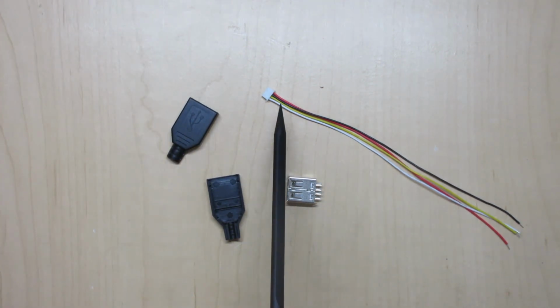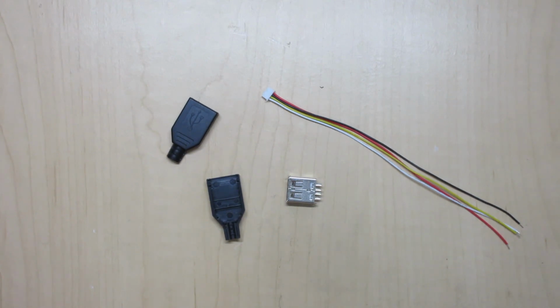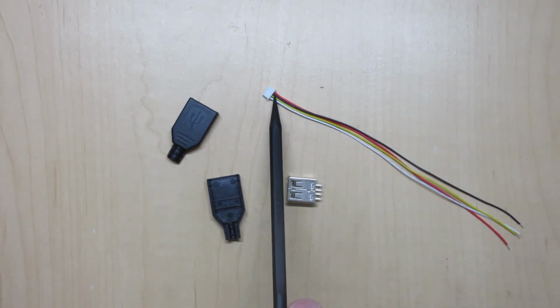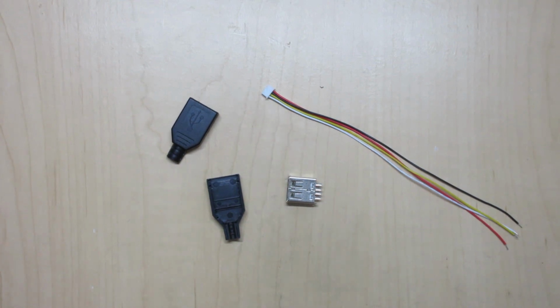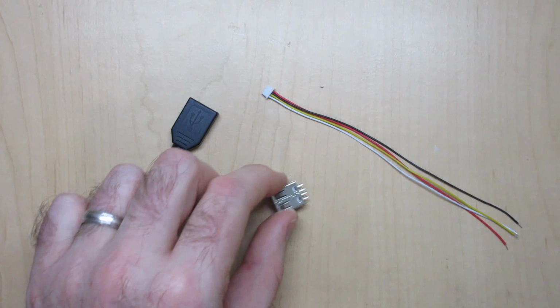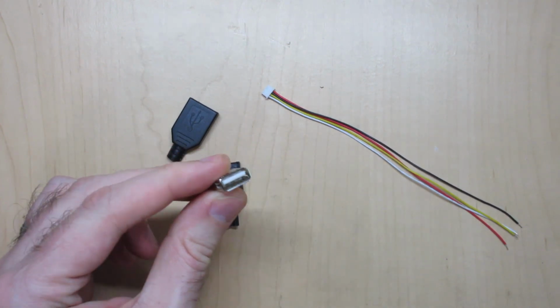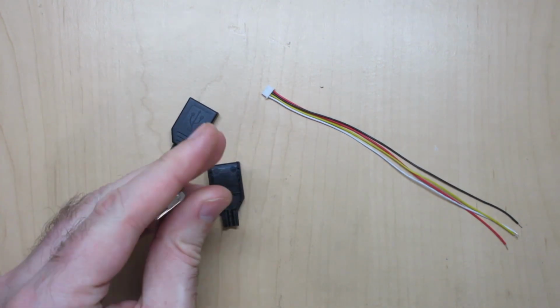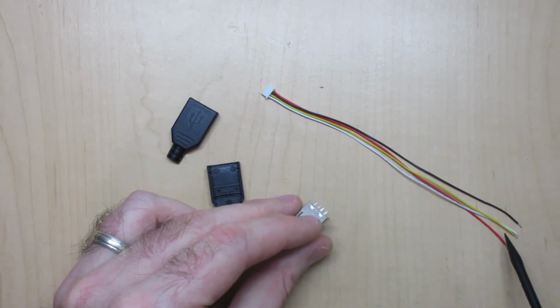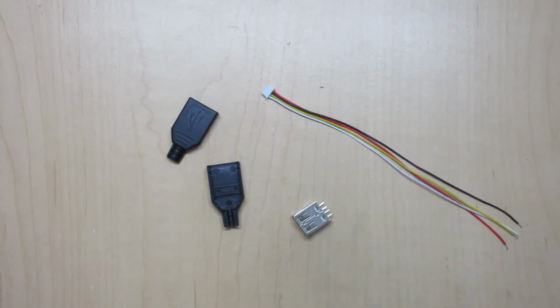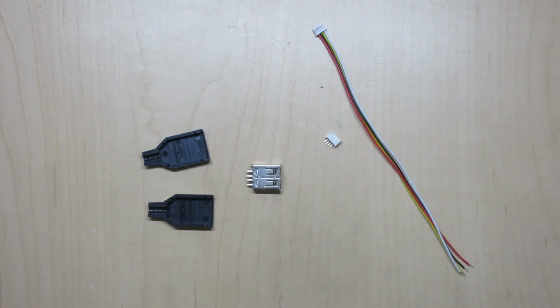Now, I opted for the pre-wired version of this cable because these are really small, and there's no way I'm going to be able to solder those terminals to these wires if I had to do that. The USB side is just as straightforward. This is the standard USB 2.0 female end, and the terminals have a slight recess in them, so it'll make soldering the ends of these wires to these terminals very straightforward. The only thing tricky about this is to figure out which wires need to be soldered to which terminals.